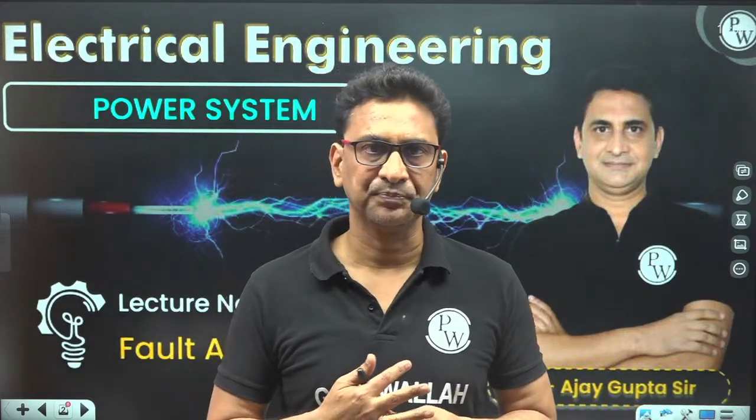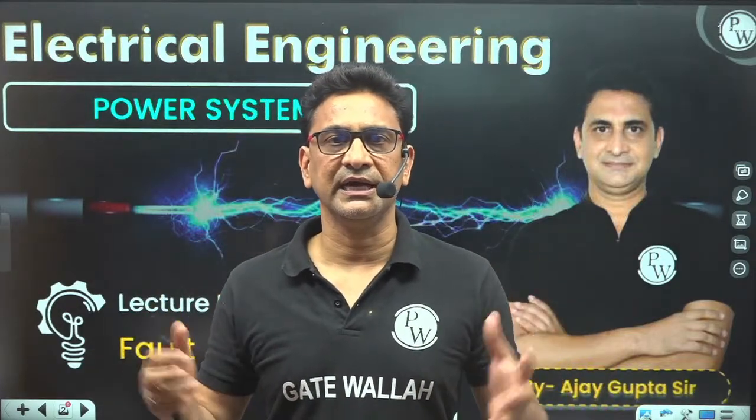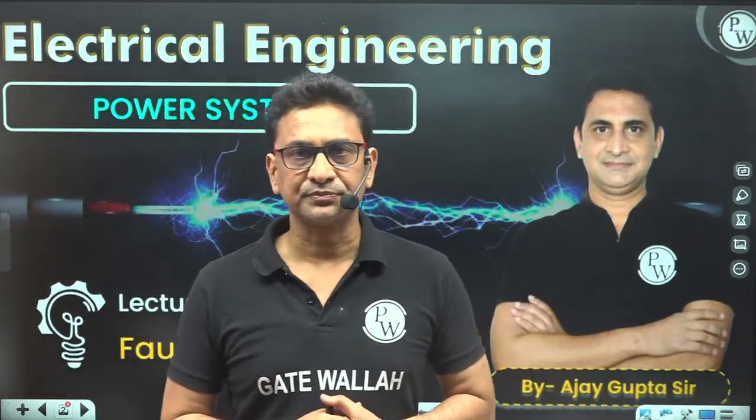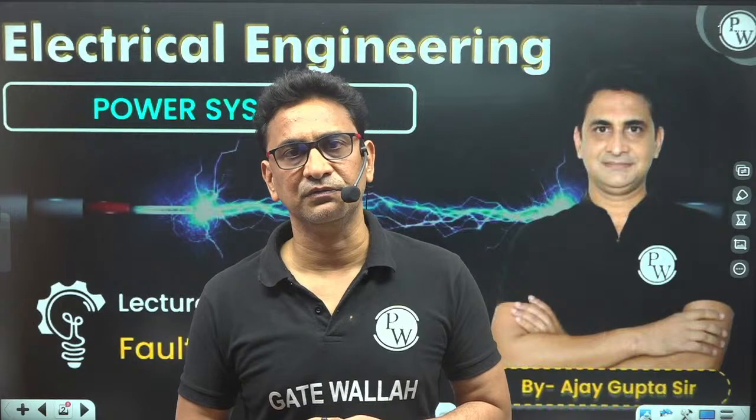And I told you, whenever a line to line fault occurs, the positive sequence network and the negative sequence network are connected in parallel with an impedance of ZF, if ZF is there. Yesterday I told you how to find out the value of the fault current, and we also derived the formula.